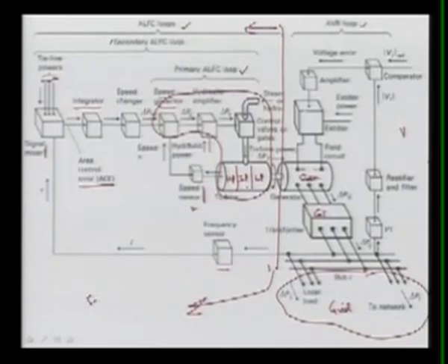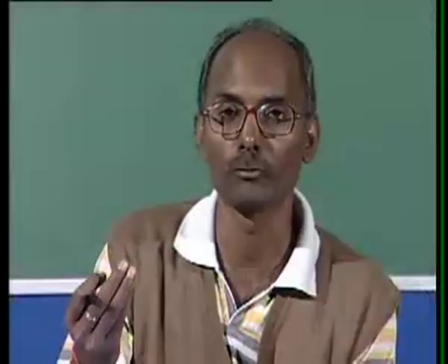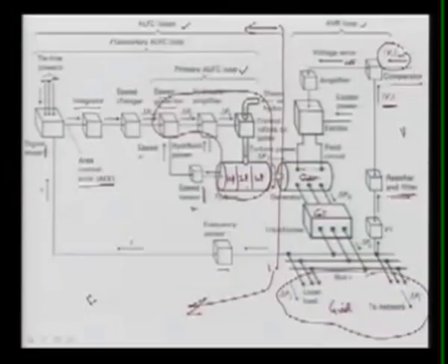This voltage is basically an AC voltage, then we are using some rectifier and filter circuit, and then it is giving your V magnitude, the terminal voltage, and once it is compared with the reference value here, the voltage reference is compared with the comparator, and that error, the change in the voltage error, is given to the amplifier. That will amplify because this magnitude is very, very small, and after amplification it is going to your exciter, and this exciter is providing the field current to your alternator here. This is basically a field winding that will be there, and it is doing that.